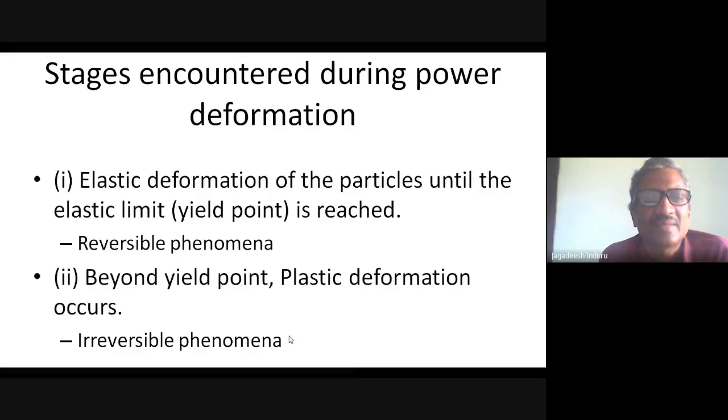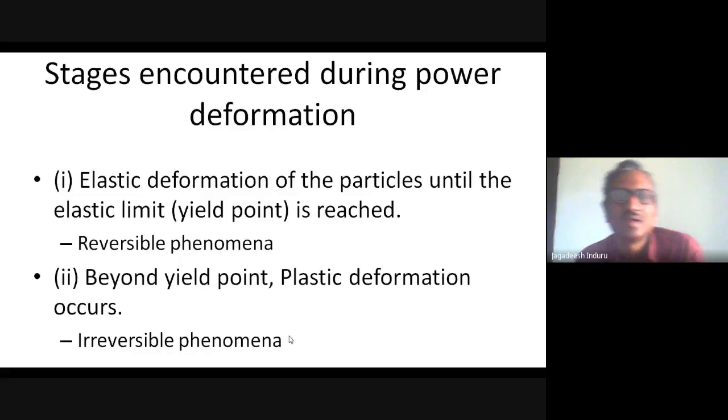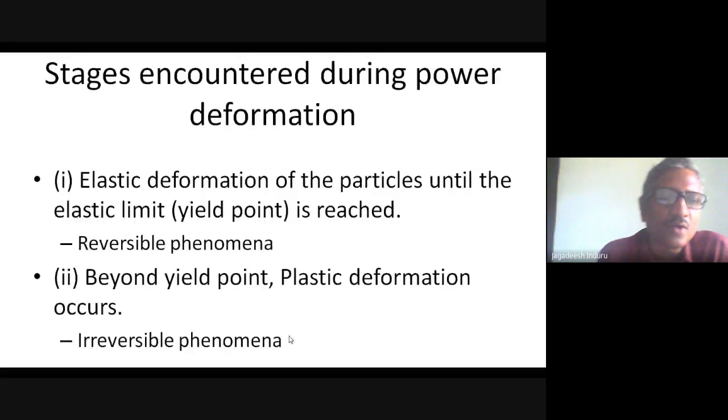It means if you want to make a tablet, you should have some plasticity in your powder. The material should behave as a plastic material, not like an elastic material. The plastic material tends to have some brittleness, it tends to get broken. But elastic material won't break, it will not have strain propagation and crack propagation, and it will come to its original position, making tablet manufacture very difficult.